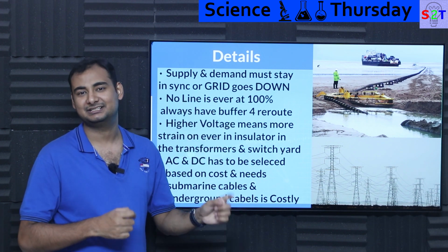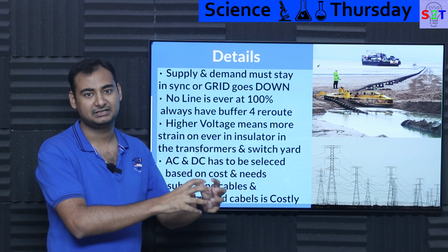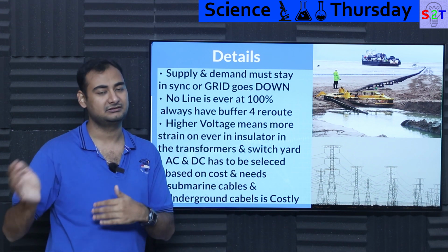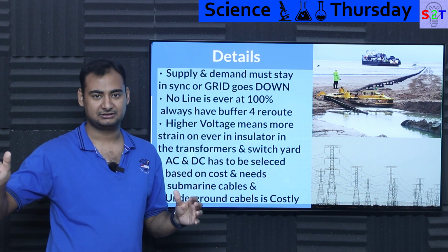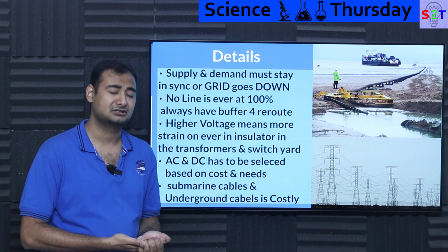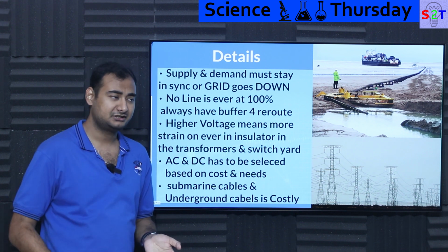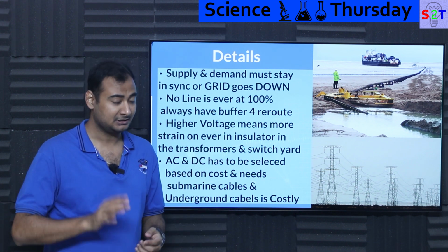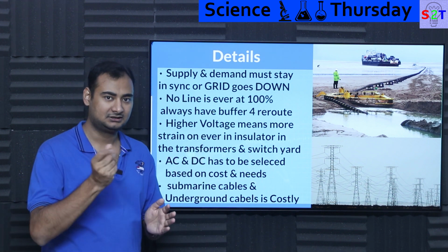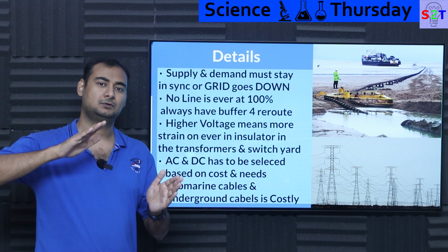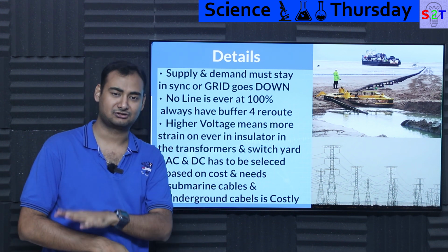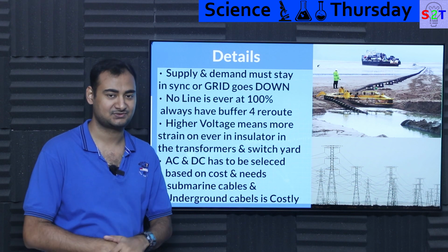At that point in time, they know there is a lot of inertial loading on that turbine. They will open up the steam valve, and it will start to spin up, and it goes the other way also. For example, if somebody is draining a lot of power and then shuts it down, for example a cricket stadium in India that consumes huge amounts of power. They shut it down, and all the turbines will start to spin up. Again, because of the mass, because of the inertia, there is a lag there. That time is more than enough for the computer to throttle the steam valves, tone it down as much as possible.